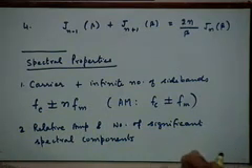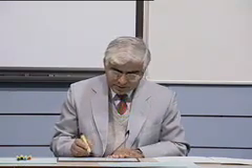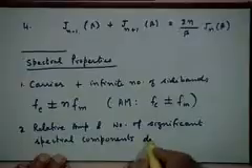Like we saw, for a small modulation index, the carrier has the largest component, other components are much smaller. But as beta increases, there can be some values of beta where the carrier component is 0 and all energy is contained in the sidebands. So which component has how much amplitude relative to each other will be decided by the value of the modulation index, right. So it depends on beta.